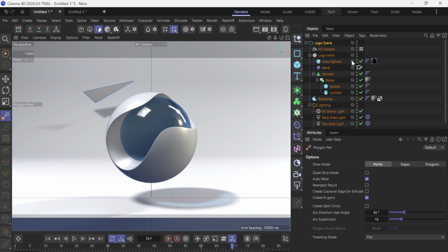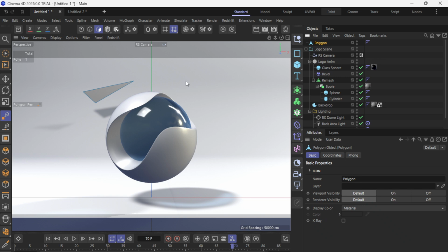Once you've set the scale and grouping the way you want, click OK. Cinema 4D will import your Illustrator artwork into the scene. You'll find the splines in the Object Manager, and you can select, rename, or reorganize them just like any other object. If the size doesn't feel right, simply use the Scale tool to adjust them proportionally. The important part is that your vectors are now native splines, ready for operations like extrude, sweep, or loft whenever you're ready to build volume.